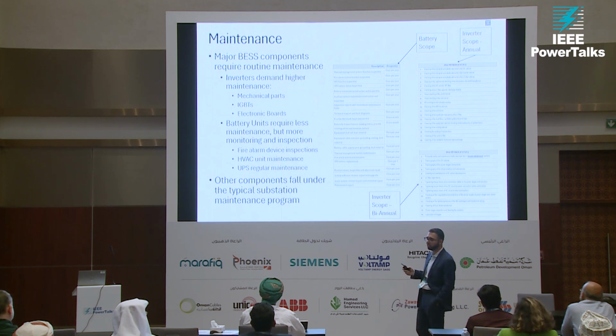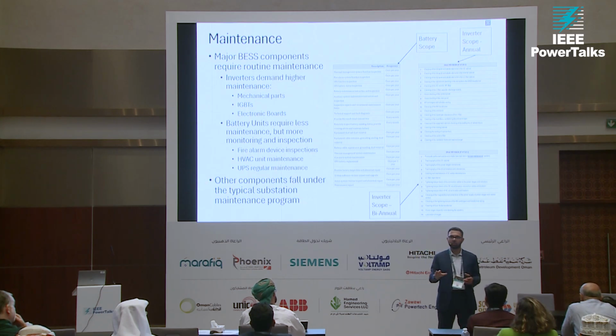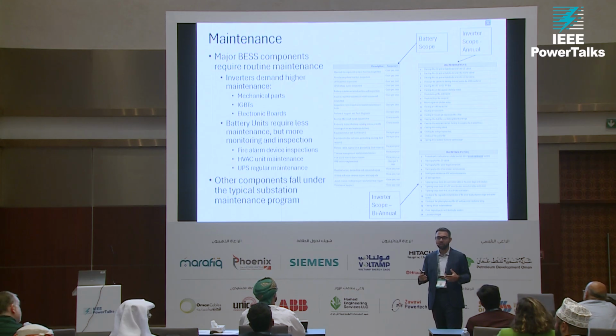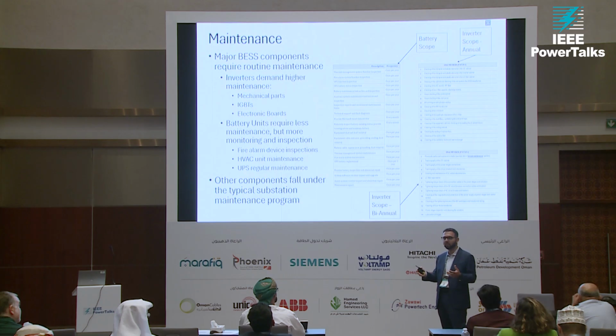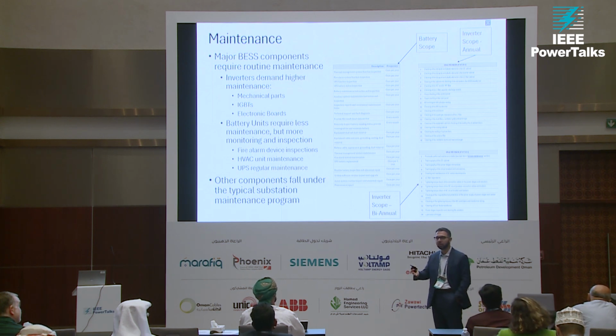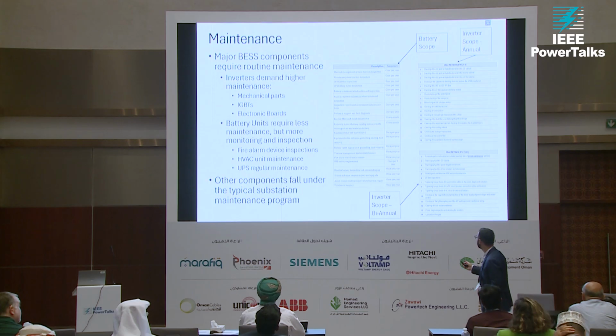container, we haven't talked about it, but each battery container has its own UPS system. And this is not a requirement in different regions, but this is specifically the North American market. The fire departments still don't accept that we have a battery that can back up those fire alarm devices. They're just still stuck in the old mindset that each fire alarm device has its own battery, even though it's within a battery. So we have to install these batteries, the substation type batteries, those that you have to replace every 5-6 years, whatever that replacement period is.